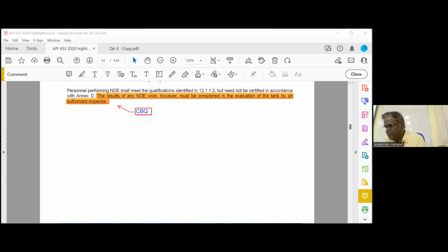But in hot weather conditions, there will be a reduction in liquid level because of evaporation. They know all these things. Okay, the leaking you can monitor easily. But what if it is an inert gas or a toxic substance? This code talks only about oil storage tanks. It does not talk about gas storage tanks. Gas storage tanks have separate rules, from API 620.